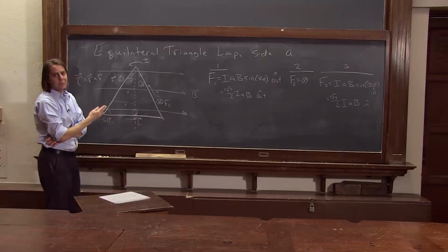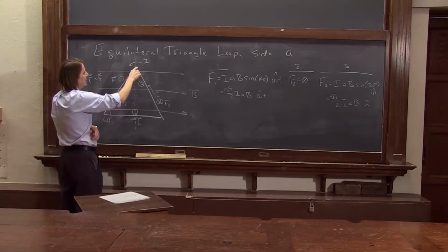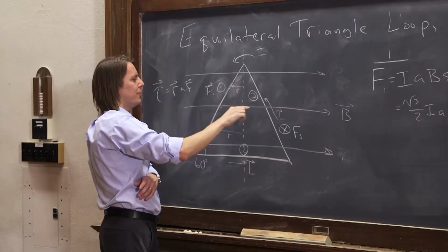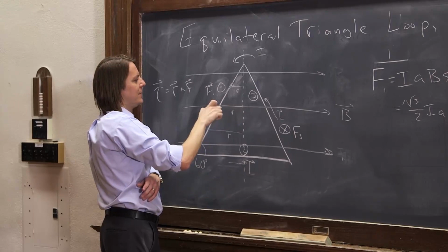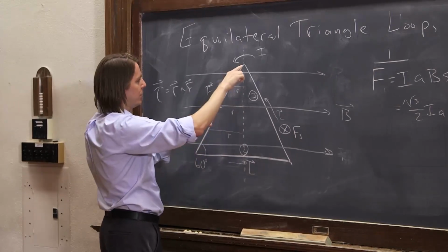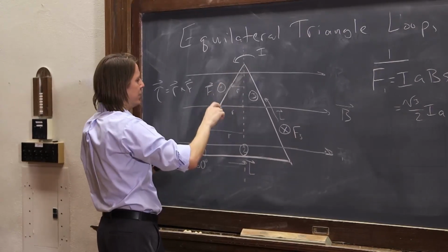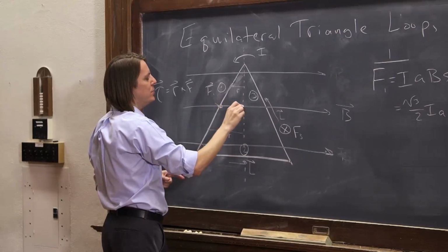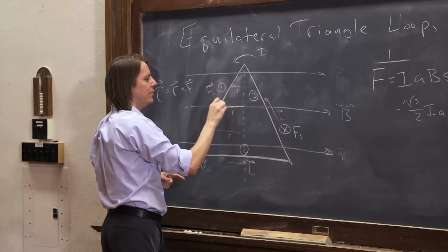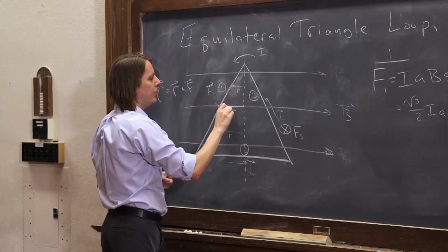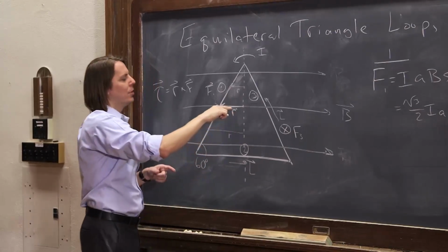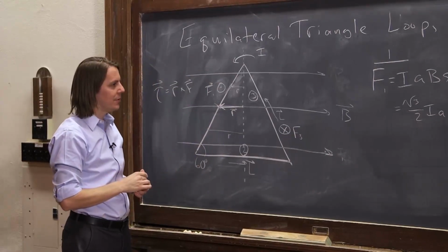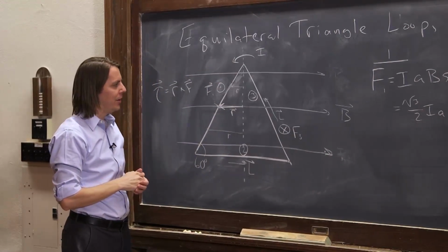So the average value is the radius crossed with the force at the center, at this point where we're at A over 2. See, here's A over 2 and A over 2. So at this point, A over 2, we want to use that value because that's the average value. So that is the radius vector we want to cross the entire force with because it's where it's the average. Okay, that's the little shortcut we're going to apply.